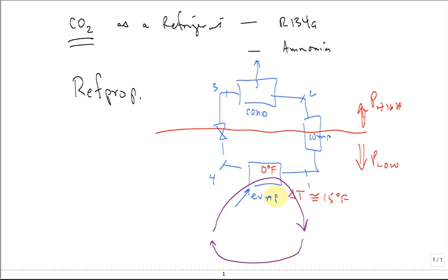All right. Out here, we have some other air coming across, and it's up on the roof, the condensing unit, and it's a hot day, and you still want to have ice cream or ice inside your warehouse, and so you have to reject heat to, I don't know, 125 degree F air. Not room, but it's maybe rooftop air.